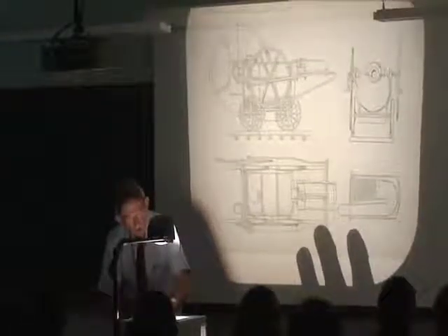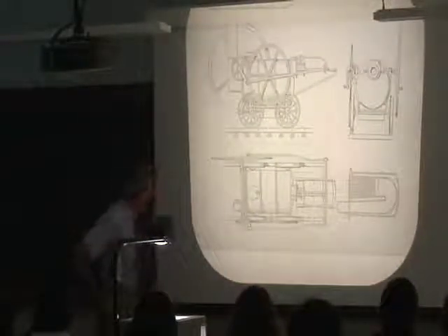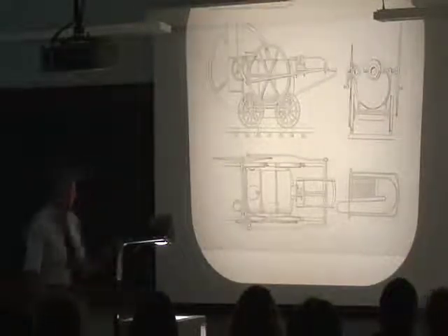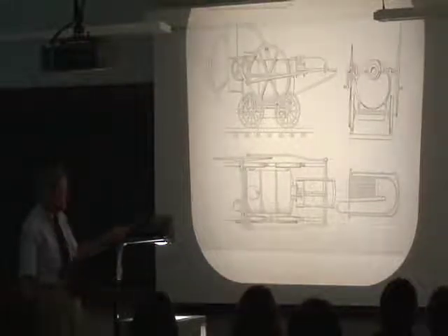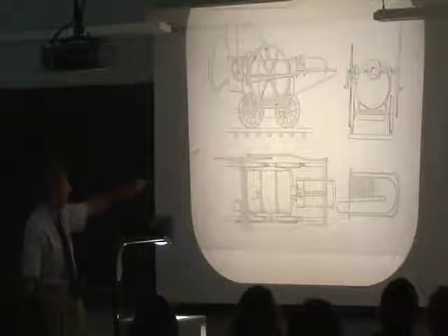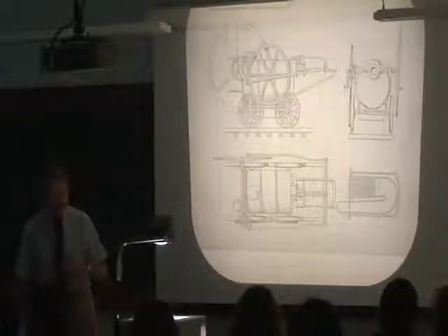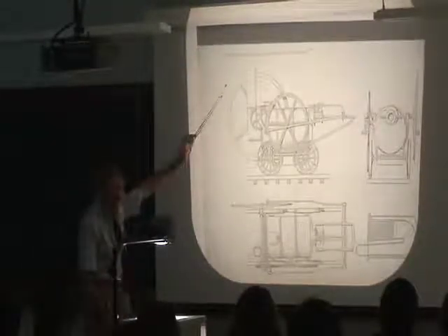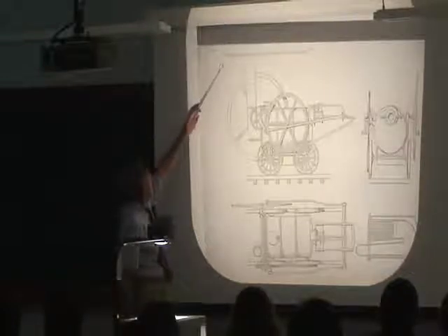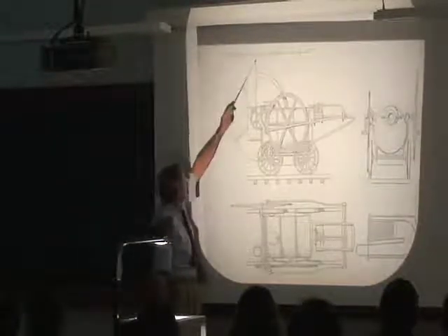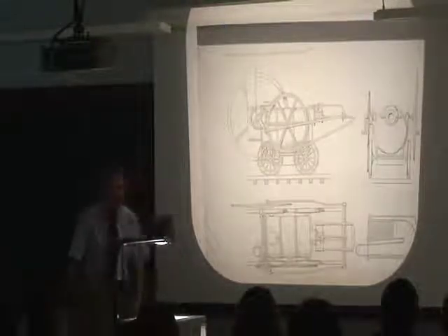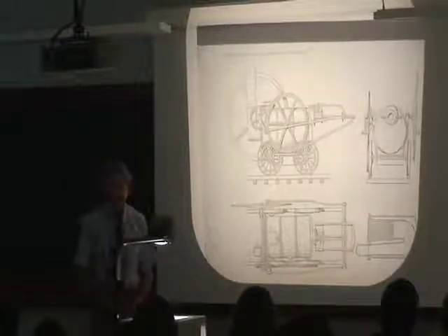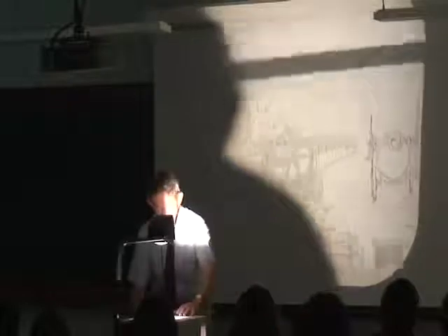Now this is 1795, and it's an early steam locomotive. But this really is the definition of the locomotive. There were some individual part drawings. I'll show you one soon. But there were no dimensions on this drawing, and you use the following. If you look, you can't see it probably, but this is a scale, and it's denoted in inches up here, and these are feet. But this wasn't a very big gadget, see. But that was the only way you had to get sizes off this drawing, but that defined the steam engine, or the locomotive.